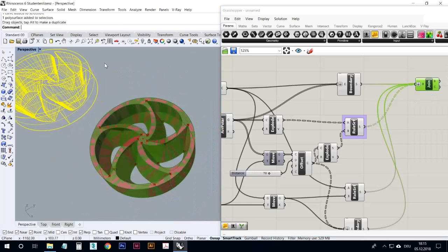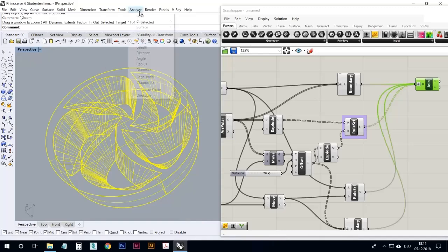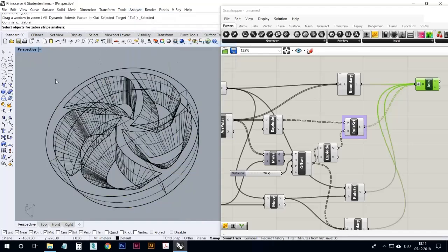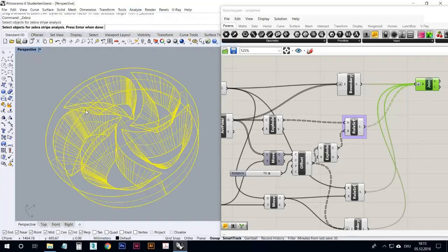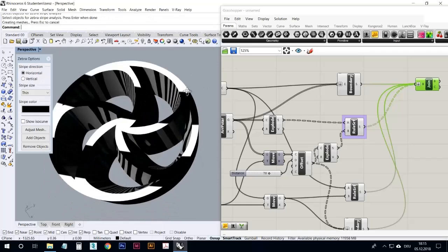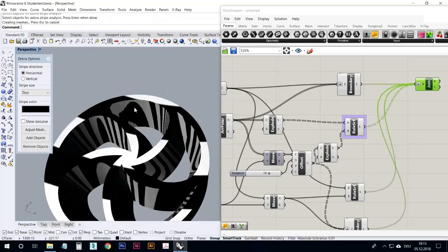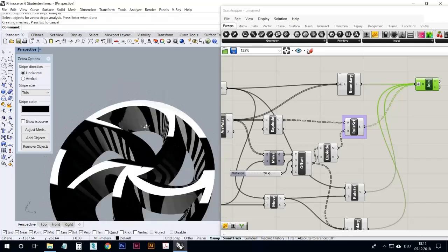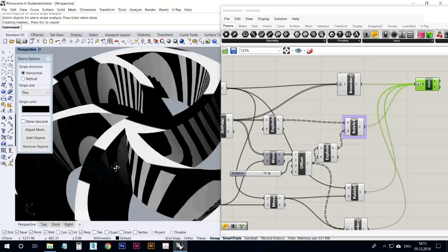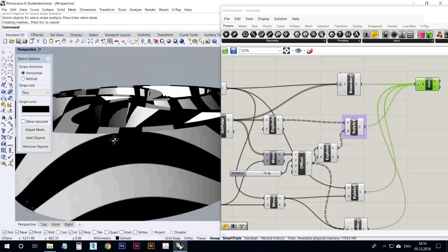And we take it out here somewhere and look at it in the Zebra viewer again. Remember that if you go here and take Zebra and select objects for Zebra stripe analysis, and then we select this closed polysurface, now we look at the edges. Beware that there's a pixel situation going on here as well. That's a bit strange, but still, this was the point where it was bad before, and now it's good. Now the surface is correct.